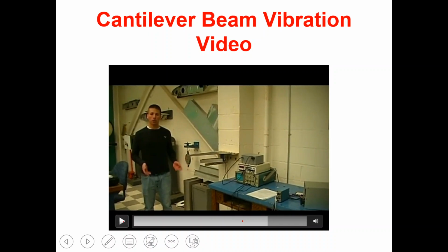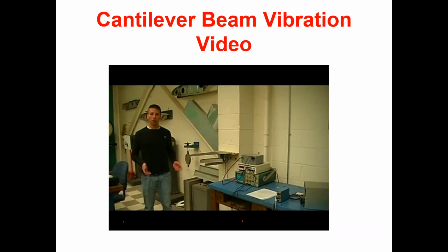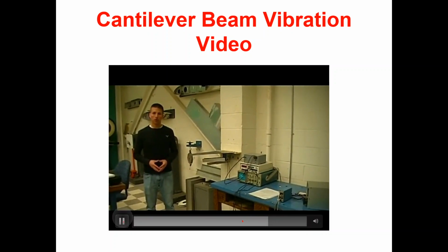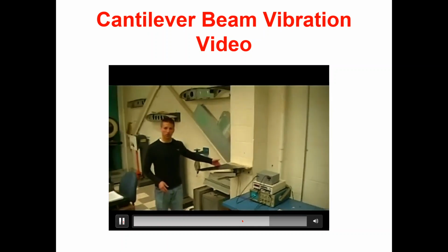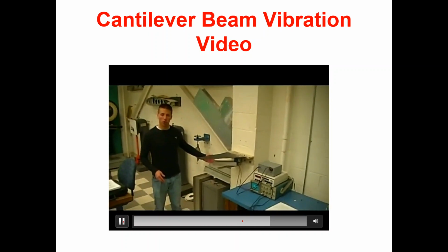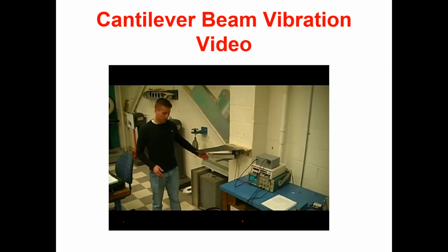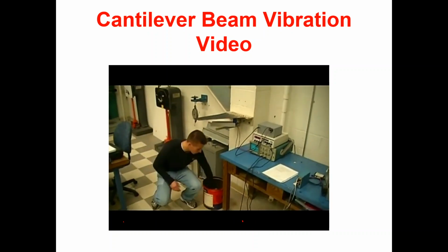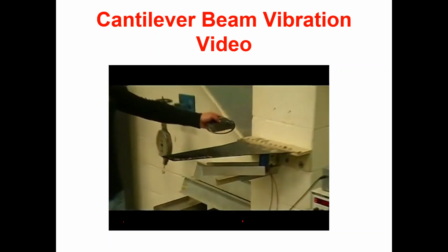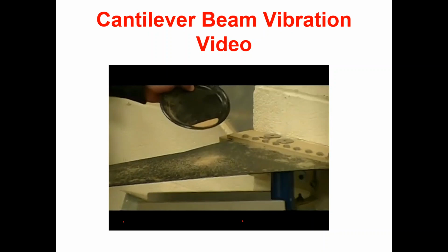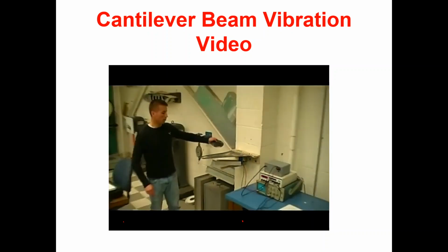I just want to show you that vibration is a very important phenomenon, as you are already aware, in the aerospace industry as well. First, you need to take the measurements as well as angles of this wing, because you will later model it in Pro-E for a modal analysis. Next, you need to pour sand over the entire top surface of the wing. Be sure not to bunch the sand up in any one location. The sand will be used to visualize the nodal patterns that will develop for the different modes of vibration we'll be testing.